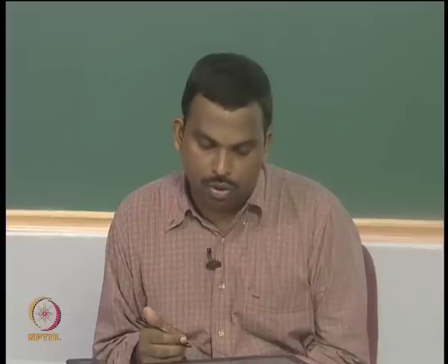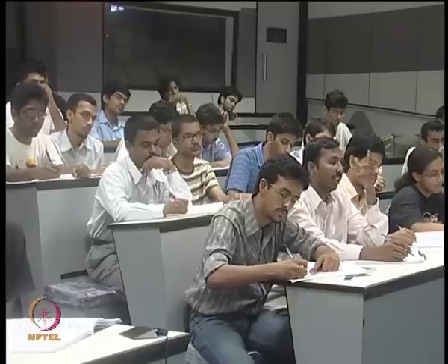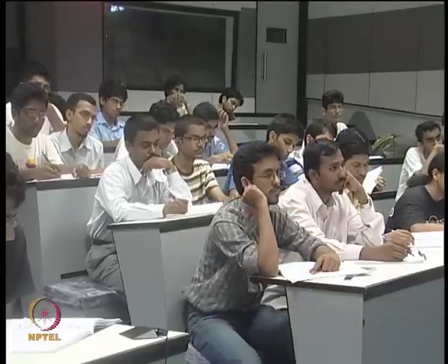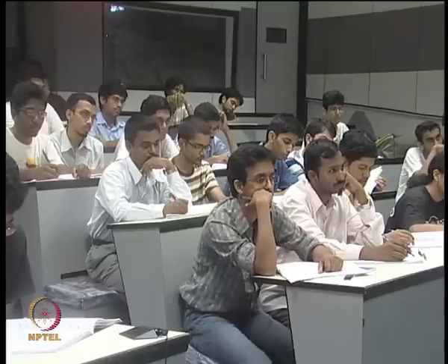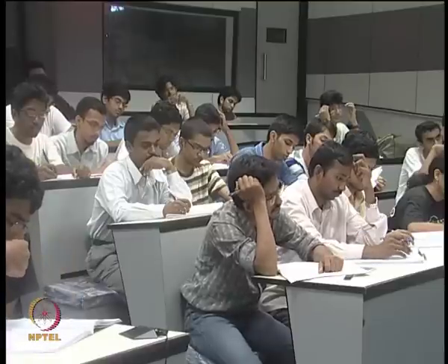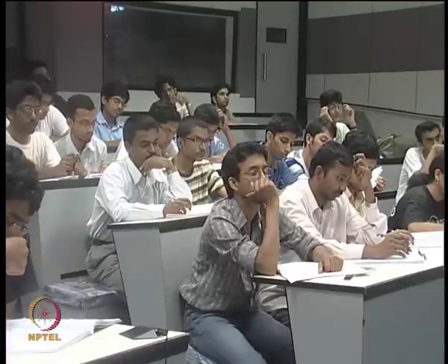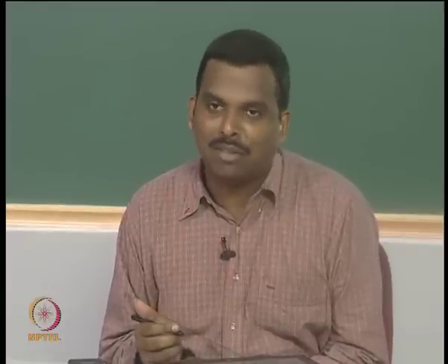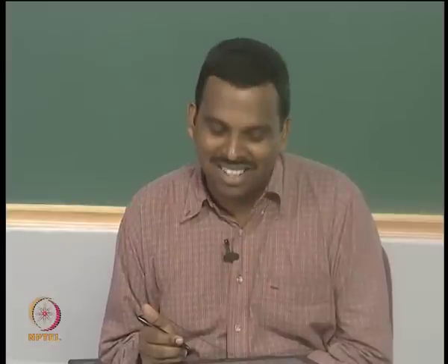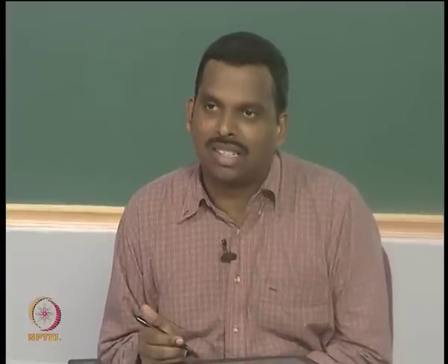So, you find the x. Once you find the error locators, how do you find the magnitude? Go back and plug into the syndrome expressions, you get linear equations for the error magnitude, solve them once again, get your answer. So, that is the idea behind the decoding. It is quite a lengthy process, and it will hardly ever show up in an exam. So, maybe you should not pay attention, but it is good to know that this is the method.